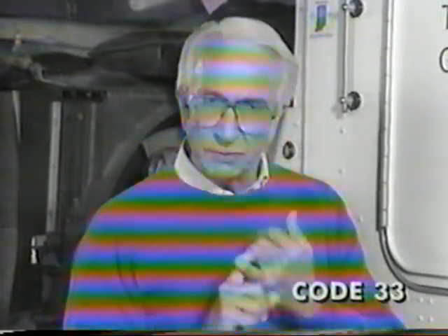First, if your service transmission light is flashing and you attempt flash code retrieval by turning the key off, on, and the service transmission light continues flashing, that's an indicator that you could have a Code 33. Or, if you turn the key off and the transmission powers down immediately without the normal delay, that's another indication that you've lost battery power.